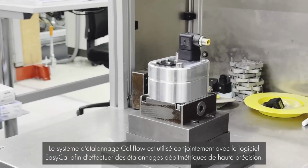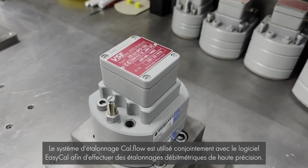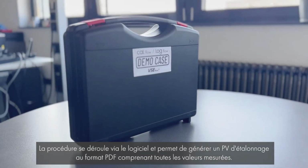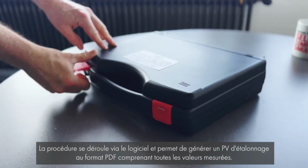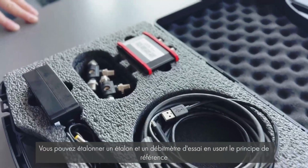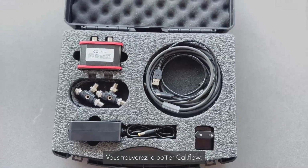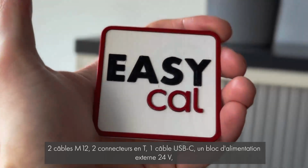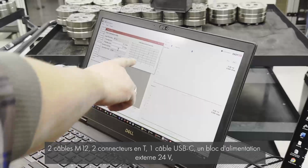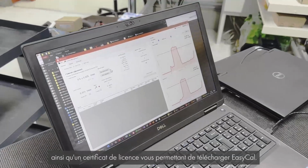The Cal.flow calibration system is used in conjunction with the EasyCal software to perform flow meter calibrations with high precision. The process is guided through the PC software and results in a PDF calibration protocol with all measured values. You can calibrate a master and a test flow meter using the reference principle and apply up to 24 master calibration points. With the Cal.flow case, you will get the Cal.flow itself, 2 M12 cables, 2 T connectors, 1 USB-C cable, and an external power supply with 24 volts, and also a license certificate which allows you to download EasyCal.